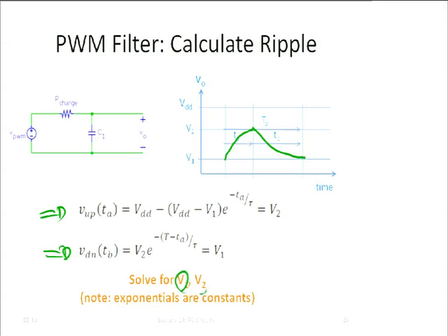We know the times here. Why do we know the times T1 and T2? They come out of the microcontroller, right? The microprocessor makes that. It sets up the PWM signal. So, of course, we know what they are. But what we don't know now are V1 and V2. So we have two equations, two unknowns, V1 and V2, and we can solve for those.